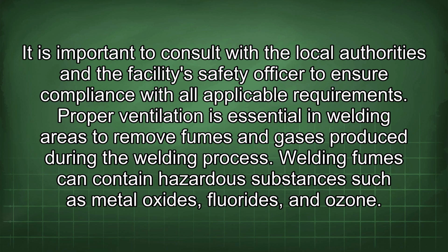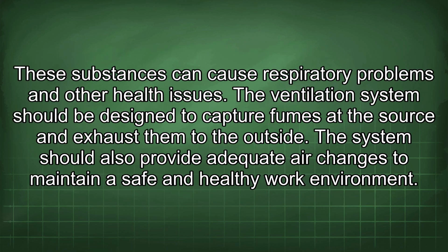Proper ventilation is essential in welding areas to remove fumes and gases produced during the welding process. Welding fumes can contain hazardous substances such as metal oxides, fluorides, and ozone. These substances can cause respiratory problems and other health issues.